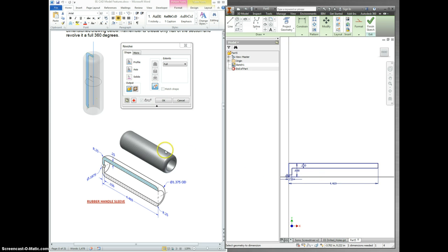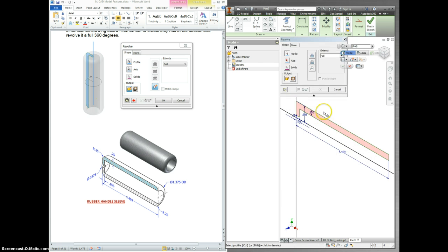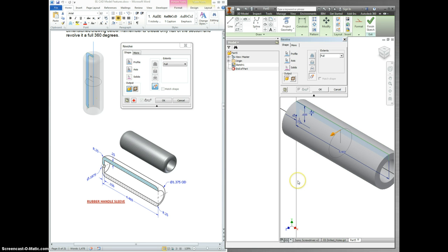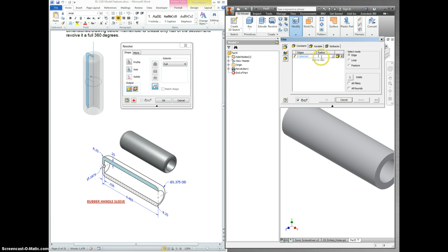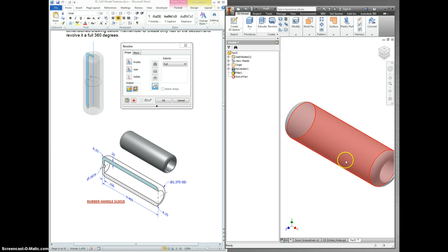So the only things that we have left are these little fillets on the outside. And just so we don't screw anything up, let's just go ahead and revolve this. So hit R on your keyboard, select the profile, click axis, click the line for the axis, click the green check for done, and now let's go to our 3-dimensional fillet, which on yours is under the modify toolbar. There's fillet. We want this to be 0.25 because it calls out radius of 0.25 on either side, and we're going to pick the outside edge of each side. Click OK and save it. You're done.